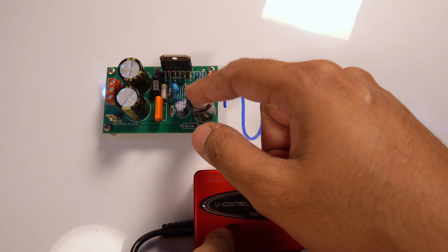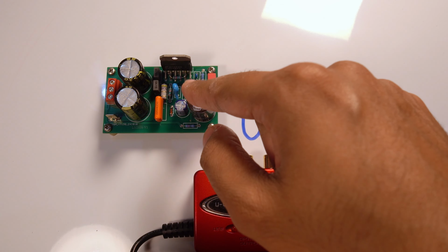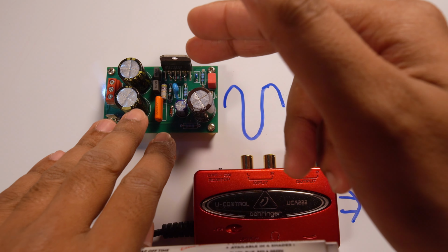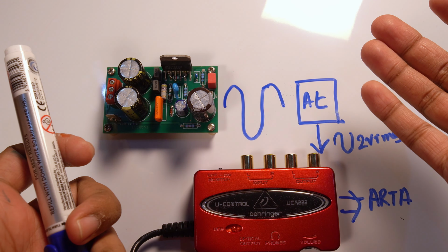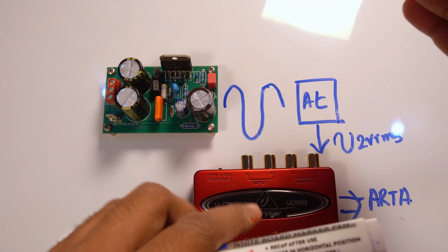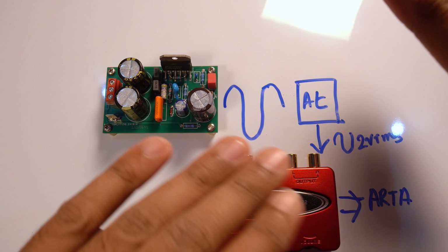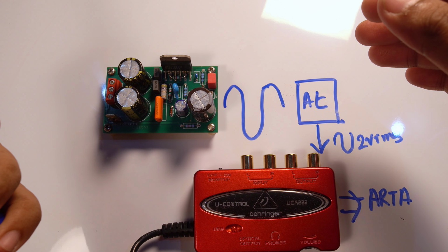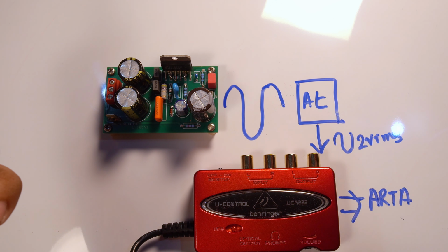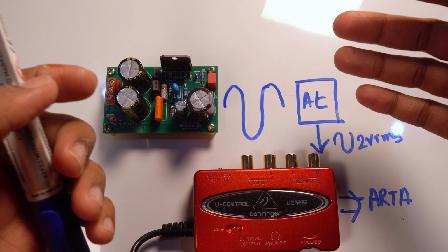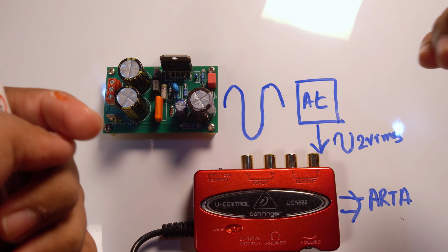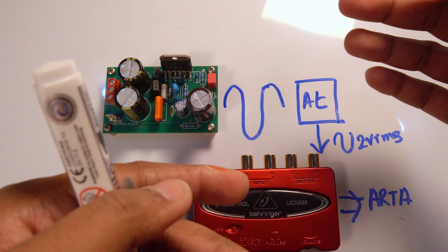But what about the signal that we are going to feed inside this amplifier? You will basically measure the input signal which is already distorted. Suppose you are using one function generator. Function generators will have a typical 0.1% to 0.3%, because function generators are not only for audio range or audio spectrum frequencies. They have to go to megahertz, and some function generators also need to go to gigahertz range. They have many other use cases.